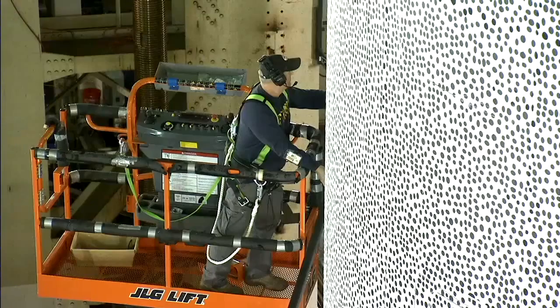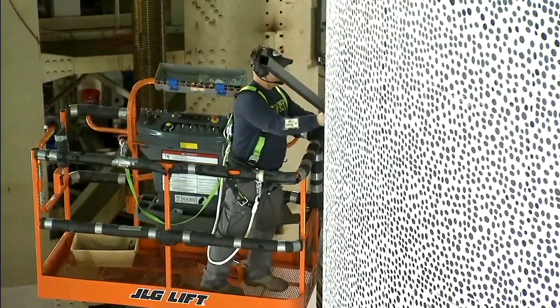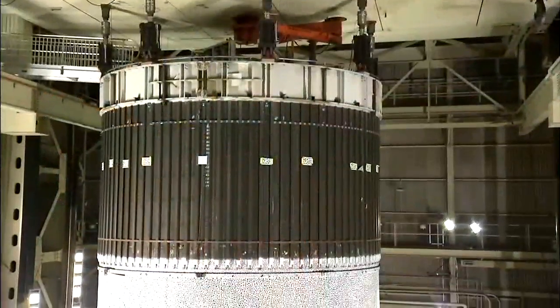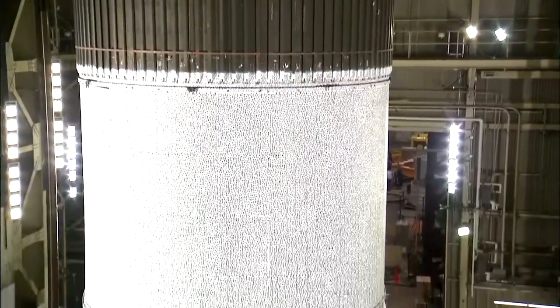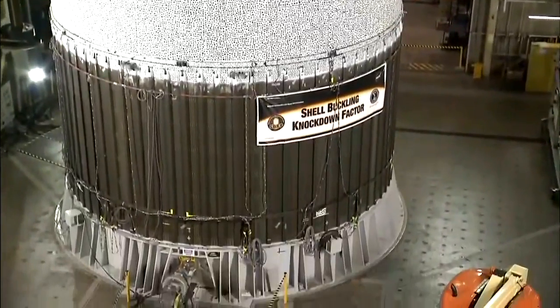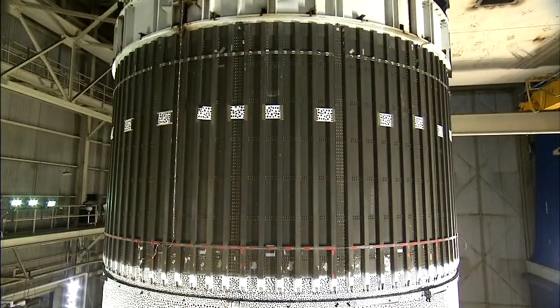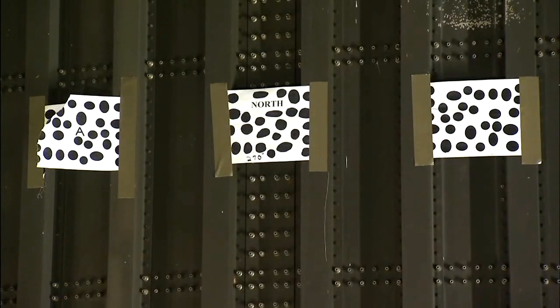That includes internal pressure associated with the fuel tanks, as well as flight loads that you would see, and that would include compression type forces and bending forces, similar to what would happen if you crushed a beverage can under your foot. The black and white polka dot pattern you see on the outside of the test article is used in a system called digital image correlation. And what that system does is we have a series of 22 cameras surrounding this test article, and it's monitoring during the test minute movements of these dots, and from that calculating the displacements of the test article.